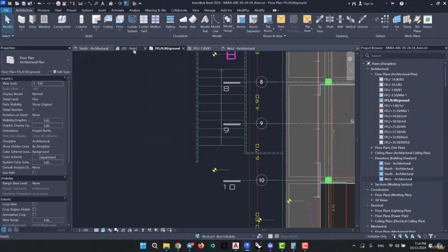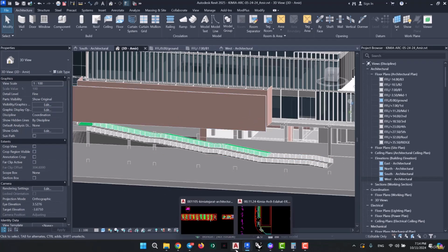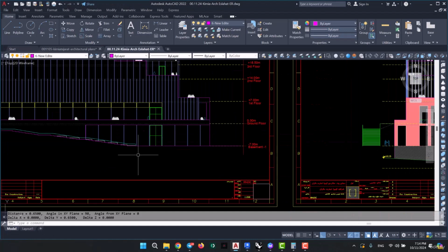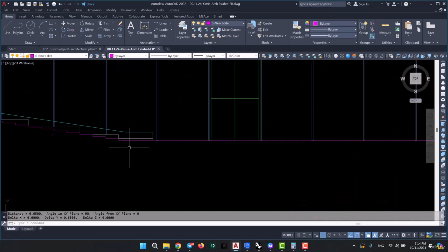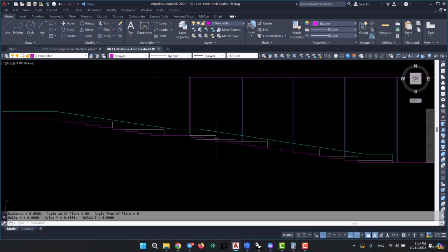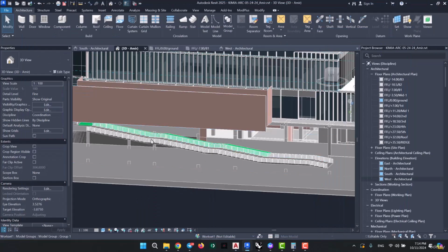Now that I've drawn these walls, I could also readjust their elevations and other dimensions if necessary. This one's elevation and the offsets are all wrong. Now, which elevation does this start at? It's at -7. So the base will be -7 and the elevation is 65 centimeters. Typically, we would need to do Edit Profile to adjust the slopes of this wall. So Edit Profile is what we're going to do to create this shape.